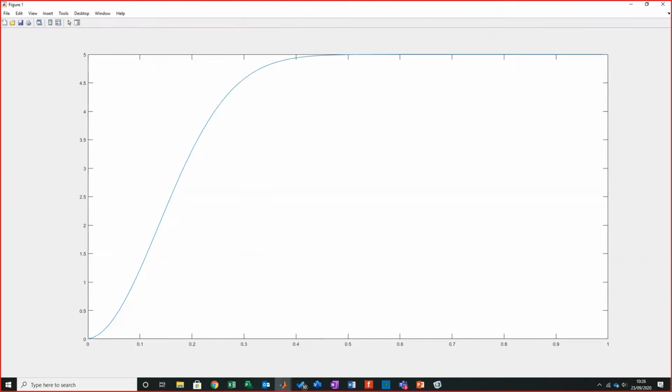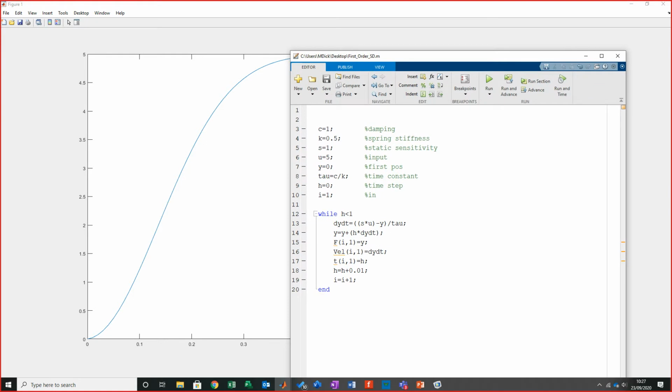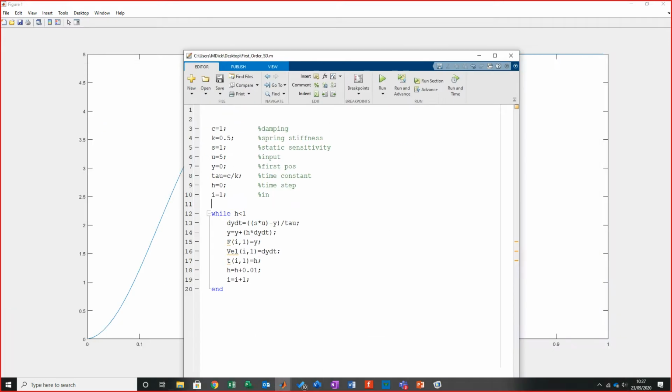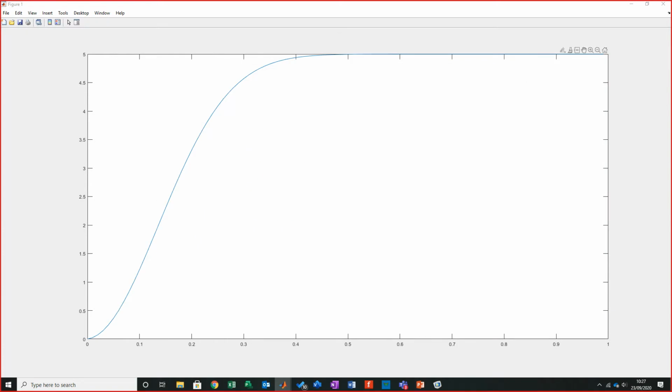Now what we've got is a particular time that it's moved. We know that the rise time between here to here is at 0.5 seconds. So the response of the spring is quite quick. If we look here, you can see the steady state where it rises and then really starts to build up. These points here is tuning for the actual spring itself. It means that the damper is probably quite strong, and that the spring stiffness is relatively small in relation. So if you look at the spring stiffness to the damper, the relation between them is quite concurrent. The damper is incredibly powerful relative to the spring, so we can change that to see what's going to happen. We can do that in just a minute, which we will.